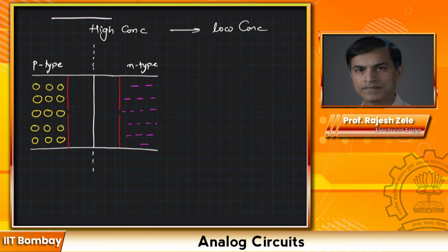So what we see then is negative charges on this side, because the electrons have arrived here, and on the other side, on the n-type, since we have lost a few electrons, you will see positive charges. Let's put circles around the charges so that we don't get confused. So this is positively charged, and the left side, which is p-type, will be negatively charged. Just so nobody gets confused, these are holes, and the magenta ones are electrons.